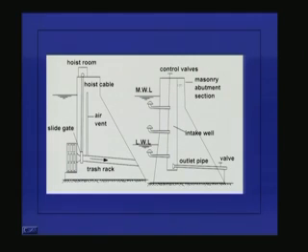So if I have a gravity dam like this, then I can have one pipe, the intake pipe, which is going through the body of the gravity dam, and there is a bell mouth here, so that there is a smooth entry into this intake pipe. At the entrance to the bell mouth, we have this trash rack structure which prevents the entry of debris and suspended matter into this inlet or intake pipe.